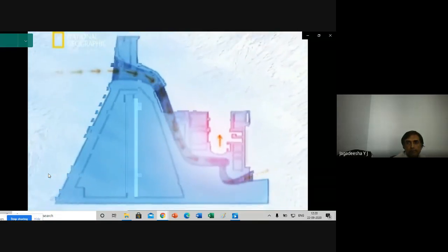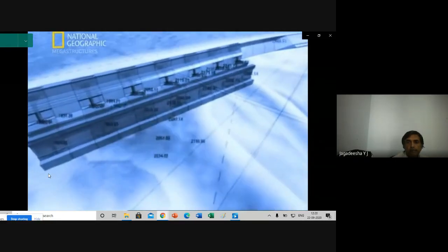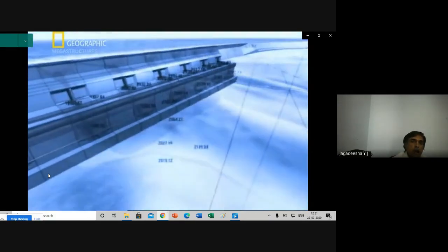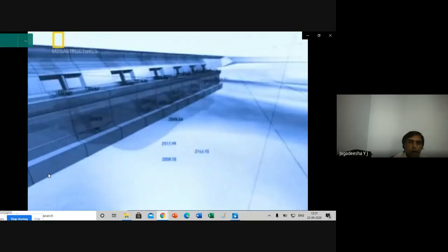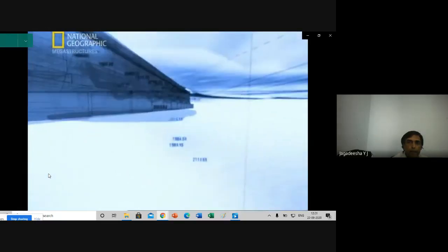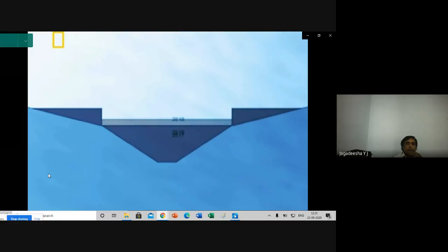Itaipu's engineers knew that the water in the dam must fall a full 100 meters to produce the promised record-breaking amounts of power. Yet, the riverbed is only 50 meters deep. The solution? Build a series of secondary dams. These raised the height of the concrete central dam to make it tall enough to do the job. But it meant running the dam structure right across the valley for 7 kilometers.